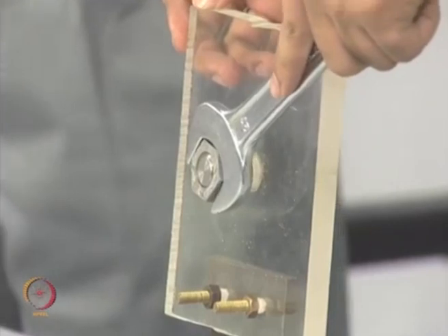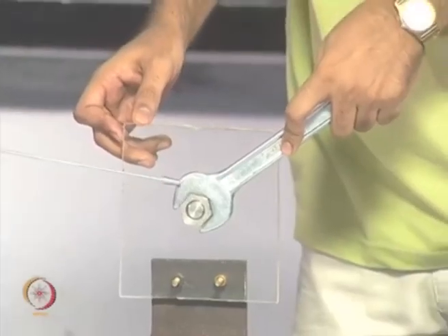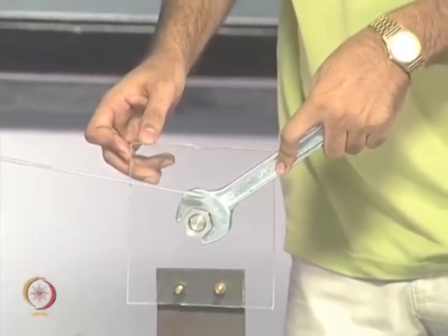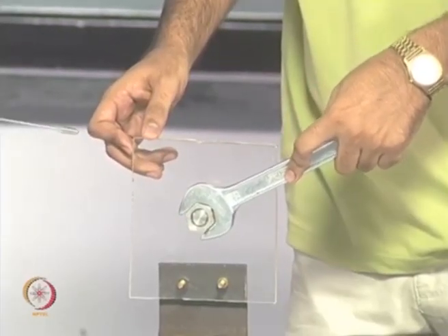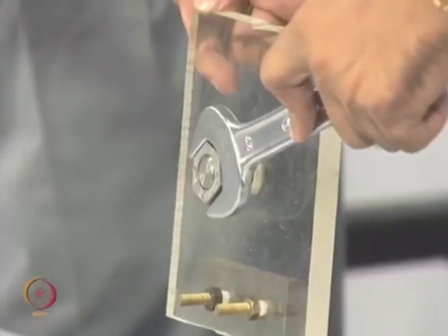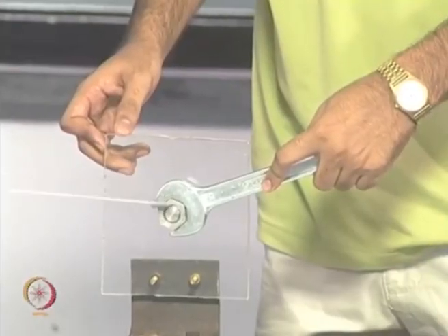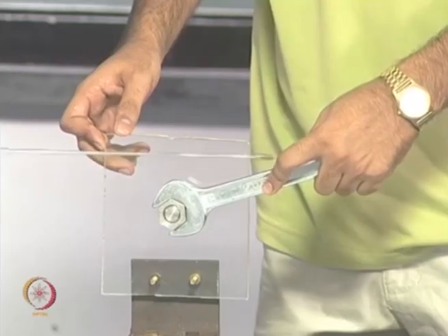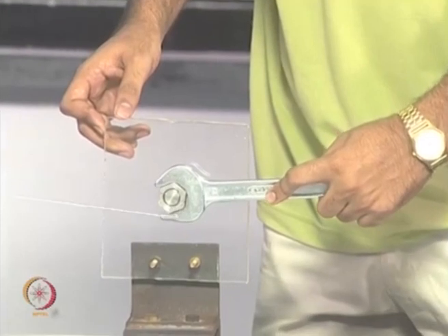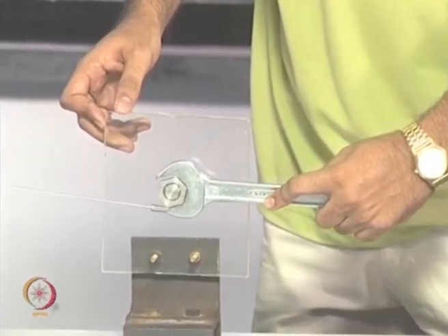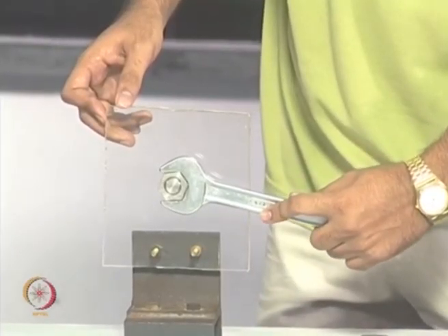and what you find here, I have this spanner and I have the nut here, and when I start tightening the nut, obviously you will find stresses are developed. Do you see the stresses here? You do not see the stresses here. And what you can say from strength of materials, because this is constrained here and you are applying a load here, some sort of a bending takes place in the member, and since you all know something about stress concentration, you could at best say there will be stress concentration in this zone and this is the load application point. So, certain general observations you could make from your knowledge of strength of materials.